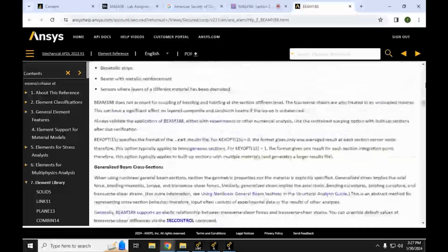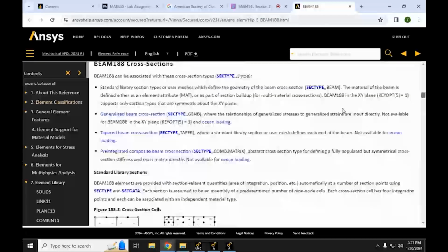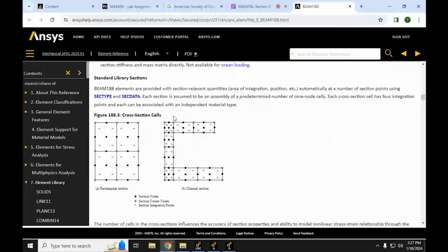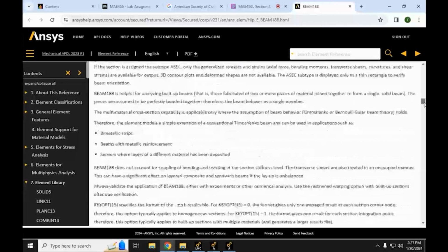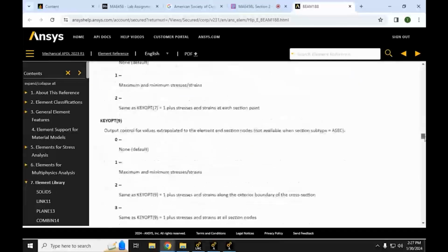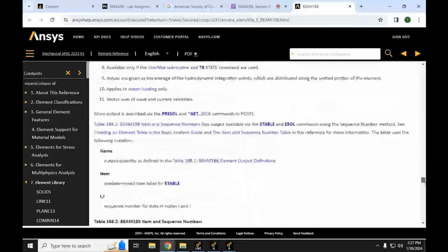If you scroll to the very bottom, you'll pass some things that may be important to point out. We need to specify now the cross section of the beam because we're accounting for the bending stress and the shear stress inside of the element. So we'll have to get a cross section. So for the I beam, we'll get an I beam cross section, and then the box beam, we'll give it a square cross section.